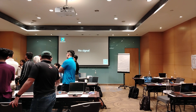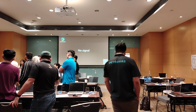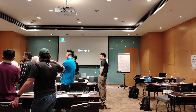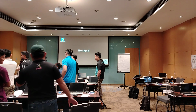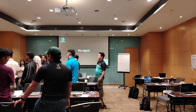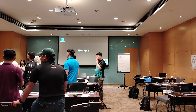When you open up the seal, the seal surface, what do you usually see? Okay, rubbing. What is causing the rubbing? Debris, yes. Misalignment, yes. Correct. So that was the immediate cause. Okay. Misalignment, installation error, some foreign object has got in already. You are rubbing it. Okay.